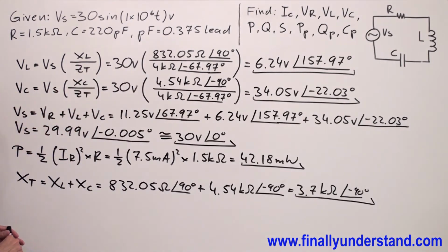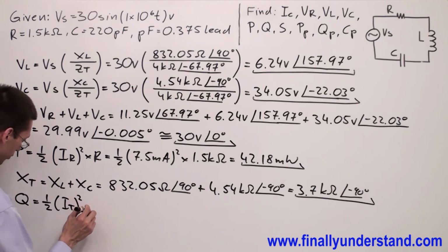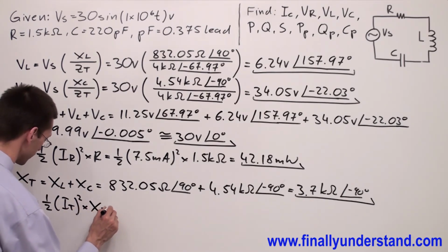So now I'm ready to find the total reactive power. So Q is equal to 1/2 I total raised to the second power times XT.